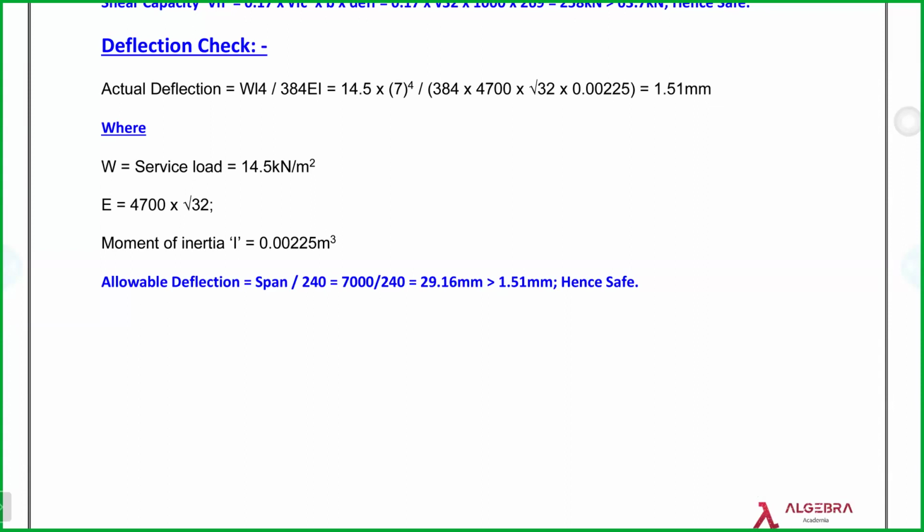To know this, you don't need to memorize 50 equations. This is very basic. What I ask is, which direction of the reinforcement is to be laid first, right? Which direction of the span, by considering what you've been calculating? Get my point? So you need to lay the shorter direction first.